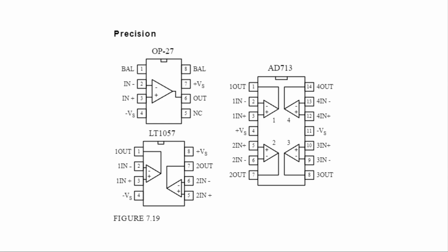Though FET op amps have lower input bias currents than bipolars, there are other features they have that aren't quite as good. For example, JFET amps often experience an undesired effect called phase inversion, where if the common mode voltage of the JFET approaches the negative supply too closely, the inverting and non-inverting terminals may reverse directions. Negative feedback goes positive, causing the op amp to latch up. It's usually best to concentrate on the specs listed in the electronics catalog. Characteristics to look for can be speed, noise, input offset voltages, bias currents, common mode range, gain, bandwidth, etc.